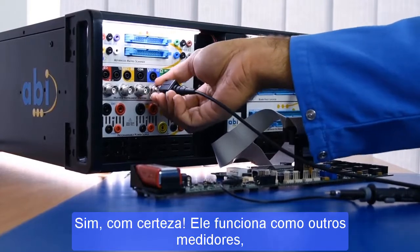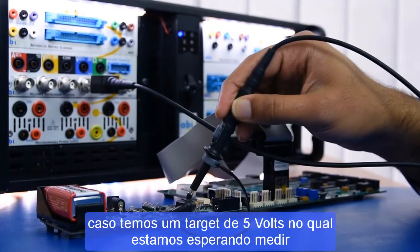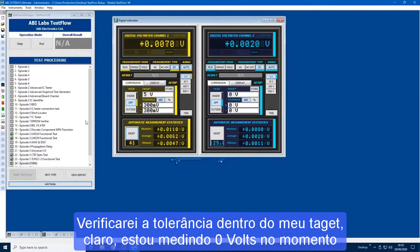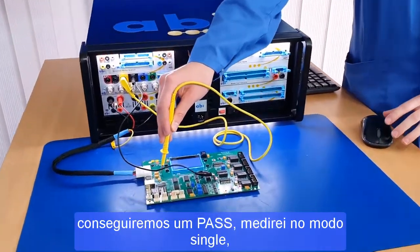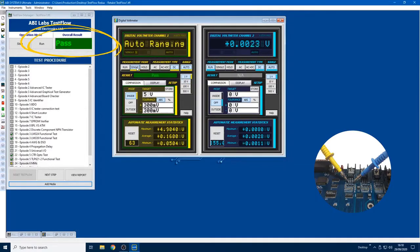Yes, of course. So it works like all our other meters. They've all got built-in comparison. So in this case, we've set a target of 5 volts, which I'm expecting from the board. As it's running already, I'll take my tolerance inside my target. Of course, I'm measuring 0 volts at the moment, so I'm going to get a fail, but once I actually measure the point I'm looking for, I'll get a pass. And I'll take a single measurement of that so I can release the probe.